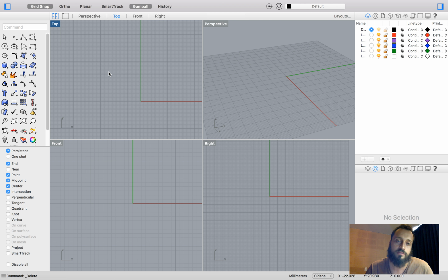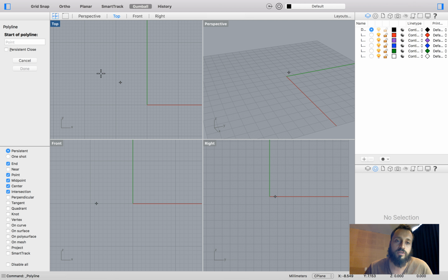For now, okay, and up here we have other options that are shortcuts that will allow us to work better and easier. Grid snap makes all the objects, all the movement, and all the placements of my polylines, circles, and objects in general be added snapping to the grid. You see now that it's not snapping to the grid, and each one of these squares is 1 millimeter. So if I turn grid snap on here, you see that it always locks into the grid.